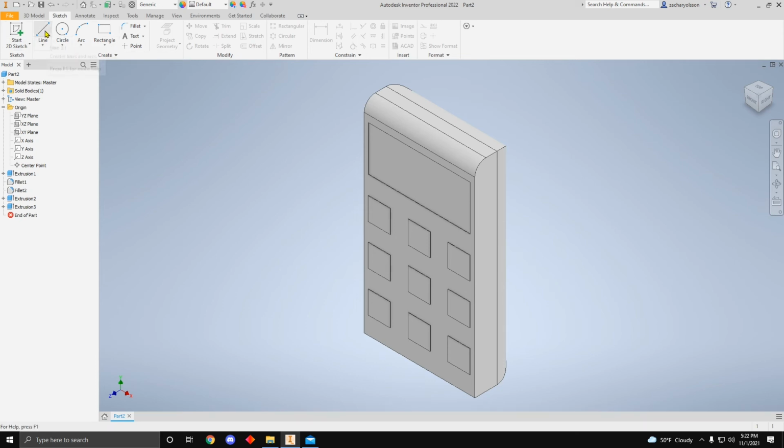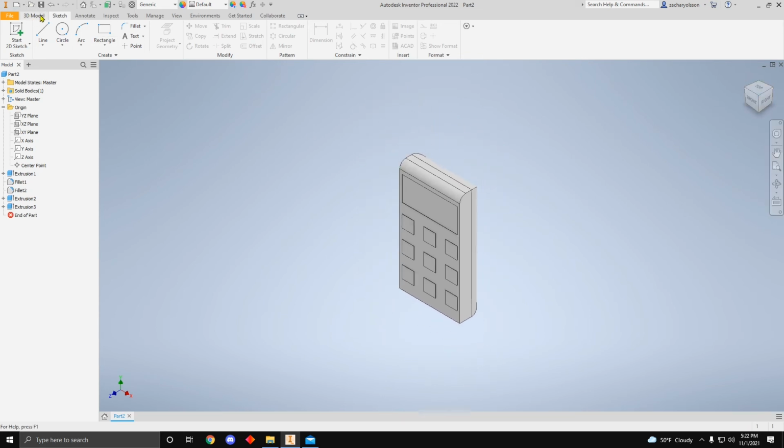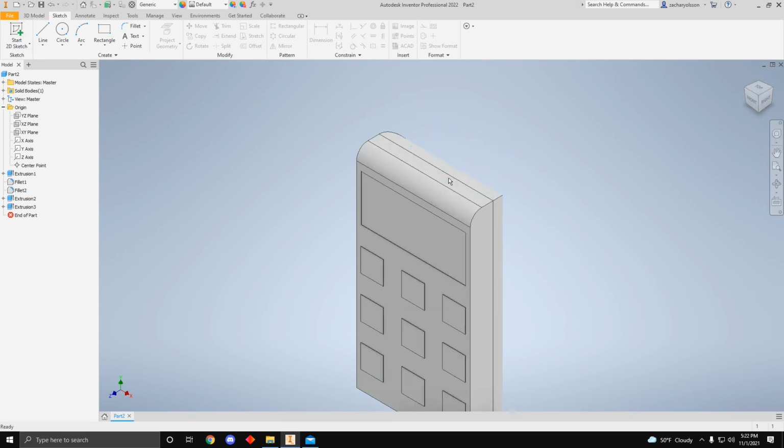But what we're going to do is go out here so we can see everything. You might think you start a sketch up there, but if you start it on top of this face right here, you can't draw towards you. You have to draw side to side, so you have to create a plane that fits. And this XY plane that we drew on is on the back of the figure, so you can't use that, because otherwise it won't sketch close to the figure. It'll be floating in the air, basically.